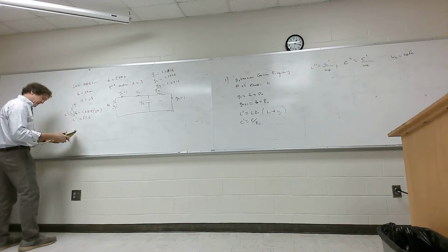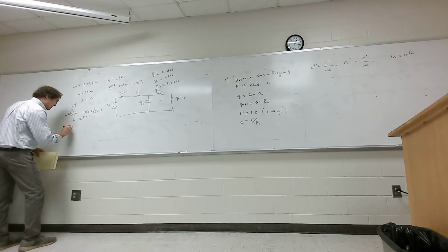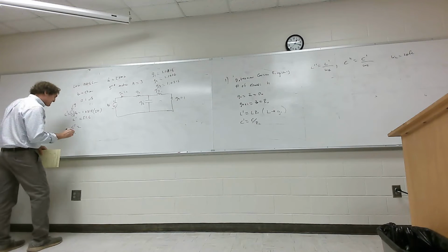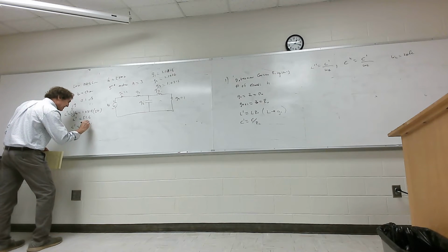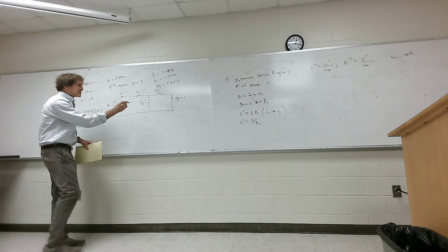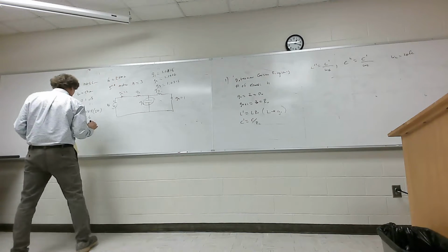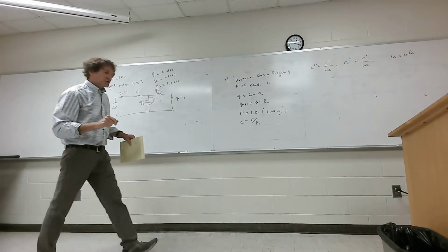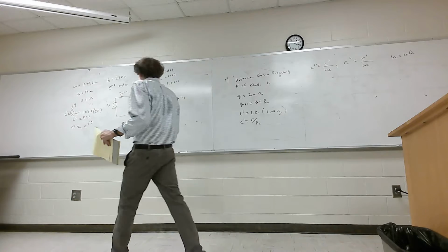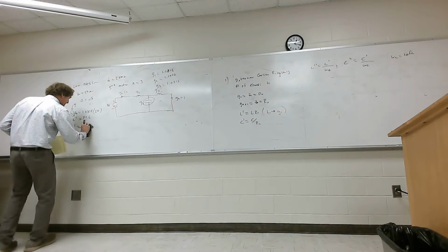That's L prime. Then we go ahead and get C prime. You can do it right over there, C over. But this is not C, that is the G value. You all follow me on this? It's going to be for this element, G2. So really what I'm going to do here is put G2 divided by Z naught. It'll be the C value, C prime, because we're using this configuration.